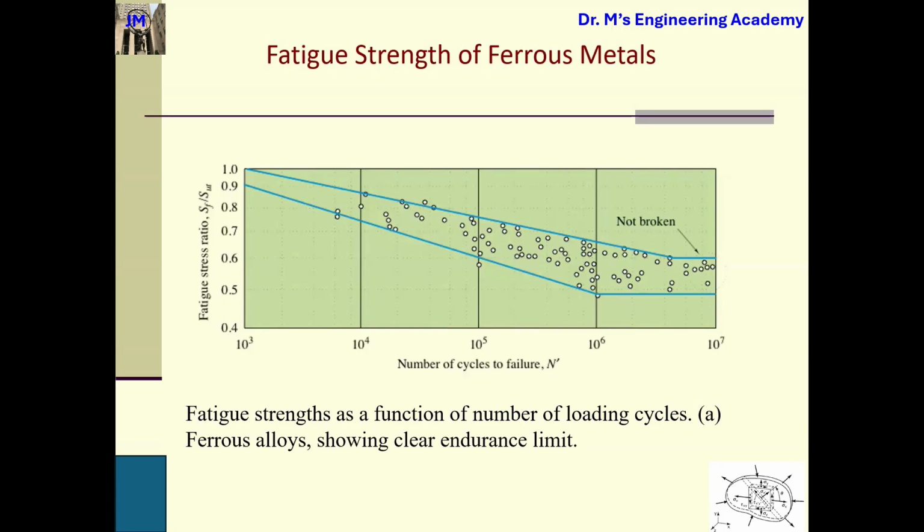Now, this is the most important thing I want you to have. I want to ask you: can you close your eyes and tell me the physical meaning of endurance limit? Can somebody volunteer? The physical meaning of endurance limit is the stress value that if you apply a stress under it, then theoretically it should not fail no matter how many cycles you apply on it. Yes, great.